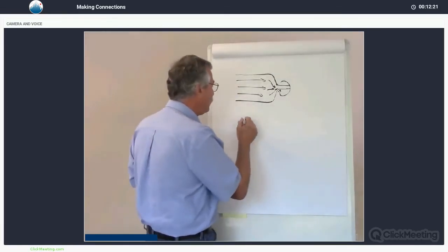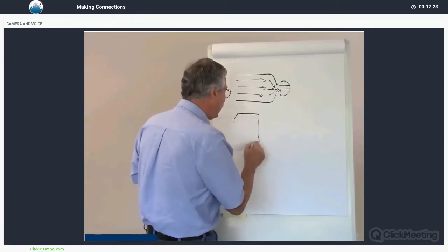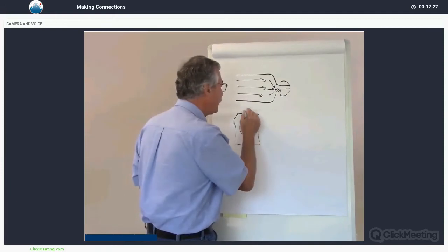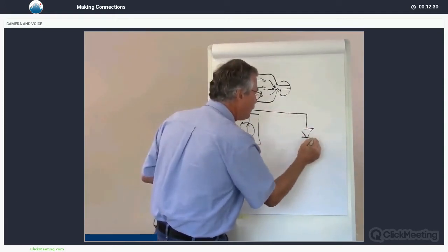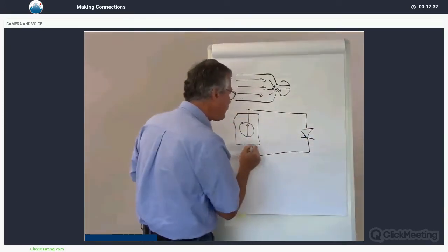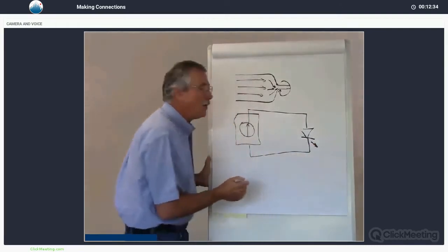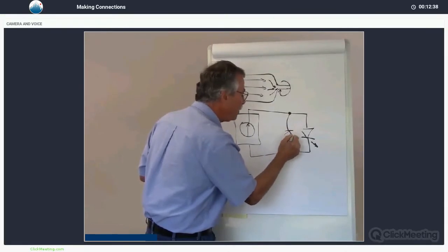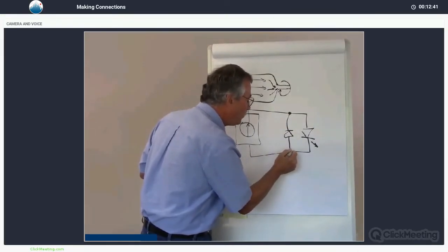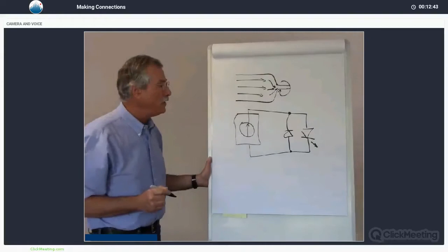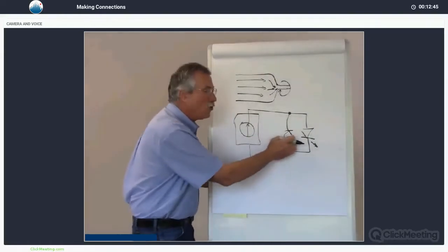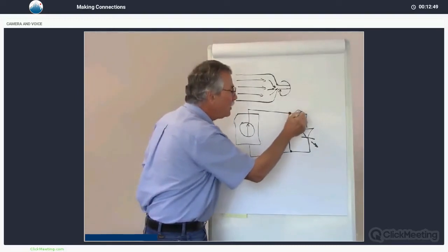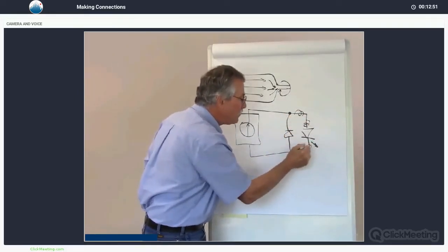One of the things that customers will do is they'll take the pulsar. Here's our current source. Here's our laser diode. And they're inclined to connect another diode in reverse parallel to the laser, assuming that we can somehow short out that ringing that takes place. The problem is we tend to forget there's inductance all over the place.